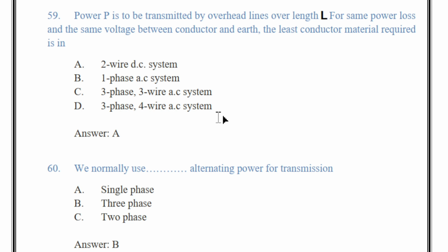A three-phase power supply can transmit 3 times as much power as a single-phase power supply, while only needing one additional wire, that is 3 wires instead of 2. Thus, three-phase power supplies, whether they have 3 wires or 4, use less conductor material to transmit a set amount of electrical power than do single-phase power supplies.